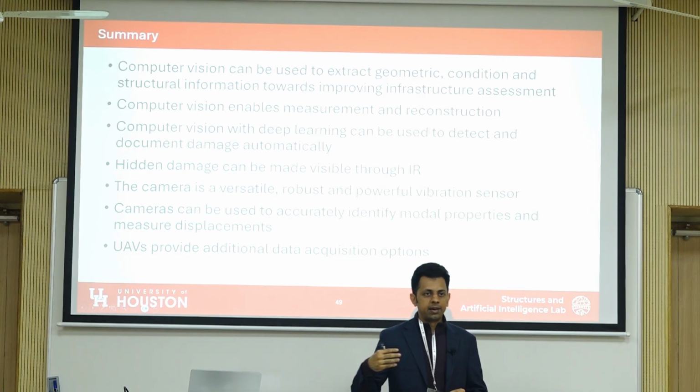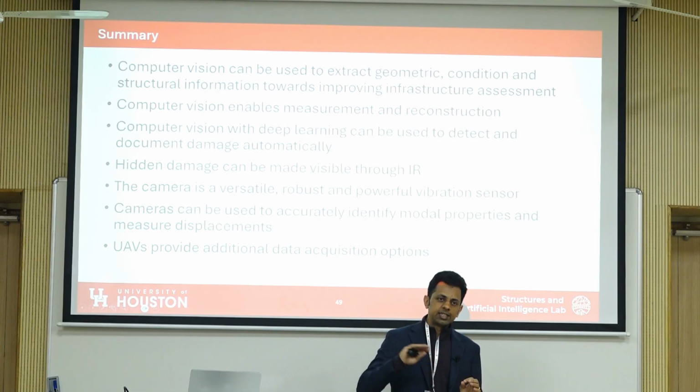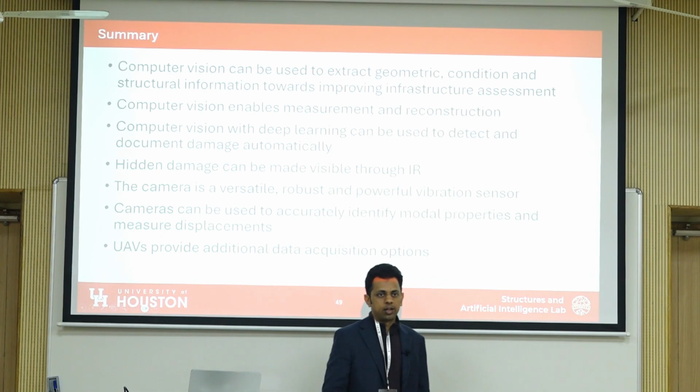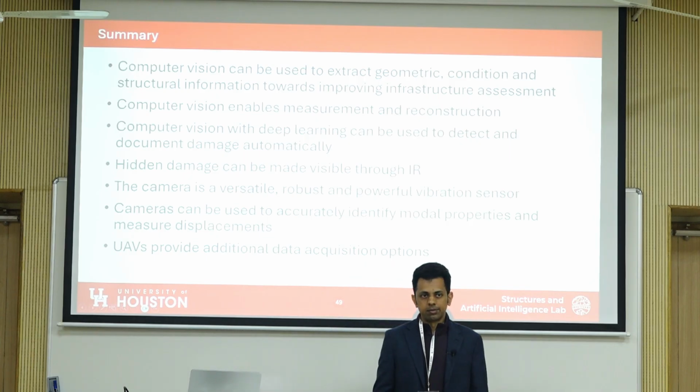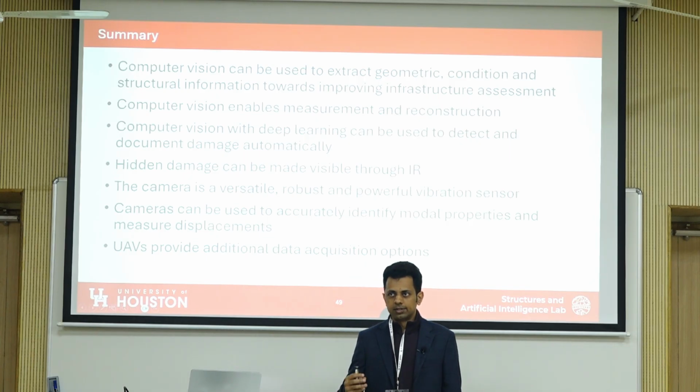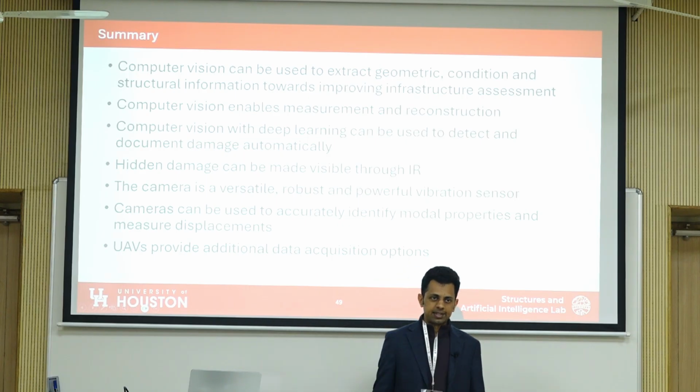But with passive thermography, like with the sun, it reaches an equilibrium state, and so at the equilibrium state there needs to be a difference in temperature that you will be observing. So that is harder for small fine cracks. But yeah, if you can get an active system there, then it makes it a little easier.